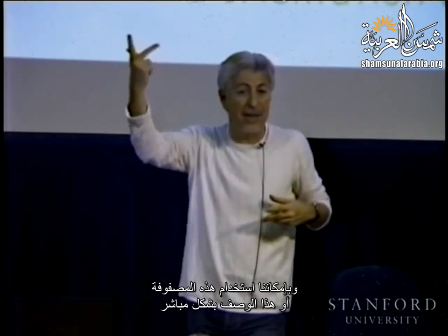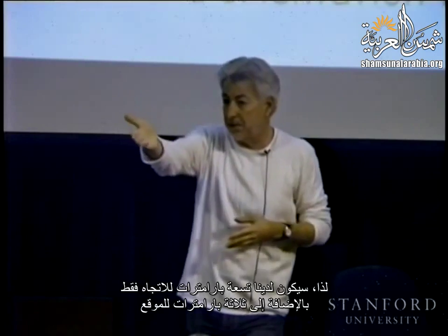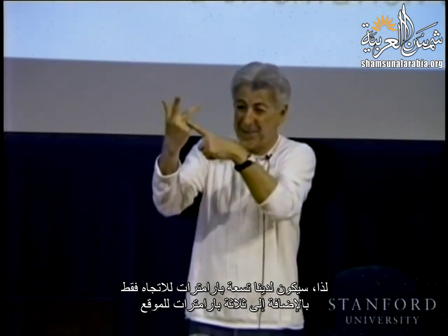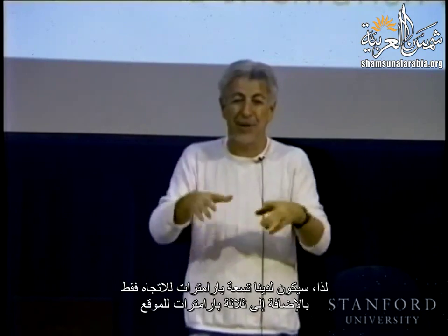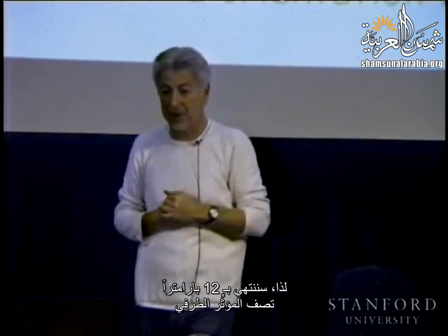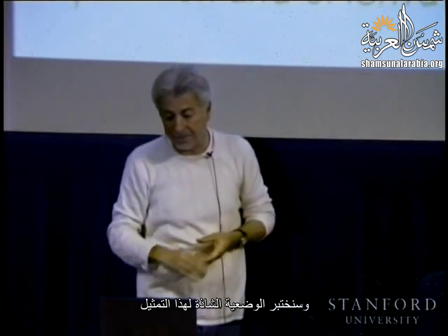And we can use directly that matrix, that description. So we will have 9 parameters only for the orientation, plus the position, 3 parameters. So we will end up with 12 parameters describing the end effector. And we will see why we will go that way, or why we go to Euler parameters, and we will examine those singularities of the representation.